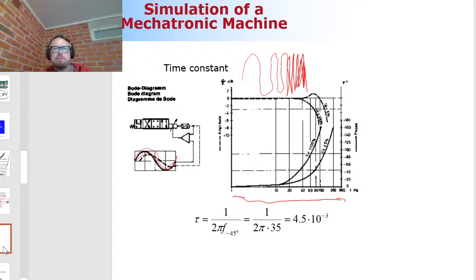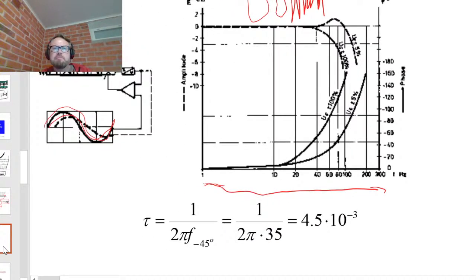As you see here, when the frequency is 10 Hertz, there's no difference between the spool position and the control signal; it is 1-to-1. There starts to be a little bit of difference at 20 Hertz, particularly when it has a full opening. So this is 100% opening. This is a 5% opening. So 5% opening is just moving the spool a little bit back and forth in the middle.